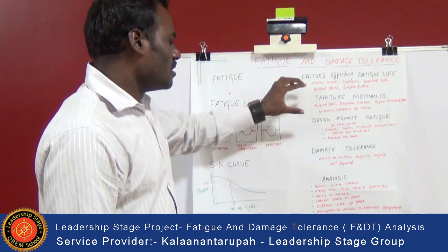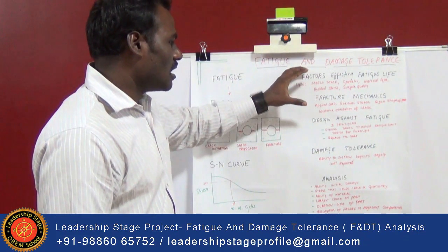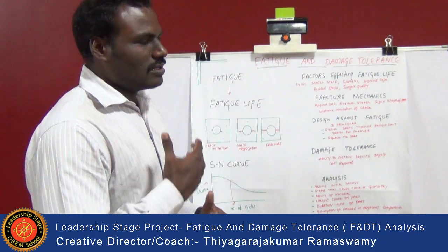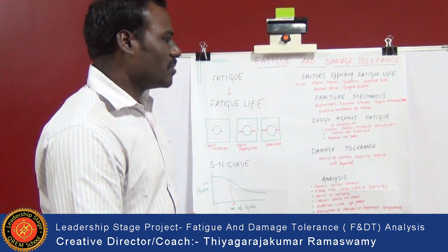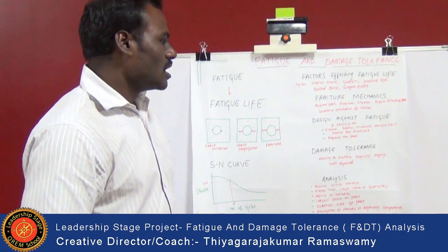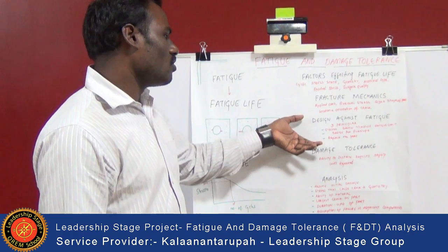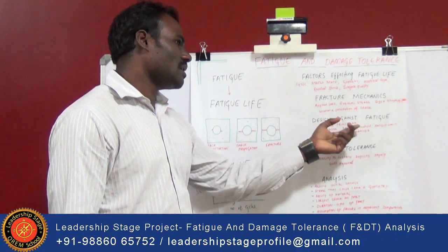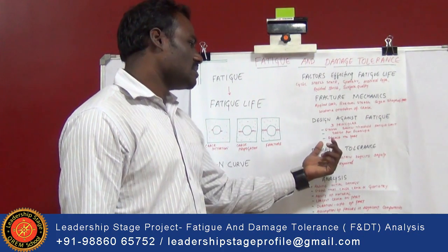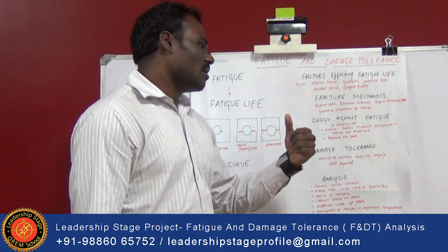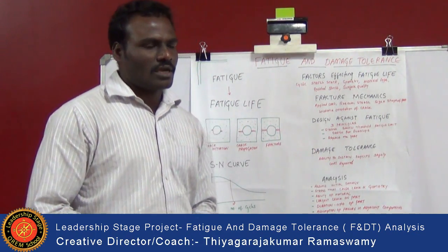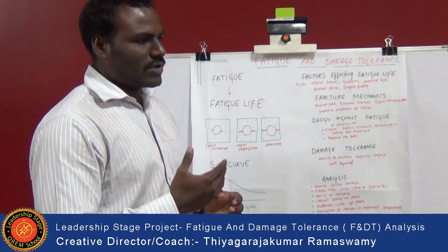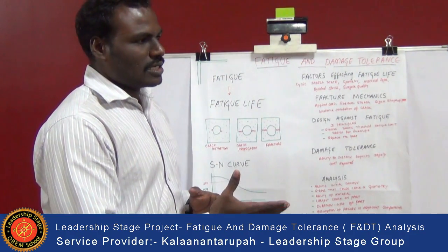Then, after finding out what the activities are which will reduce the fatigue life of the material, in order to improve it, we need to go for a design against the fatigue life. Here, three principles are carried out. First, the stress below the threshold fatigue limit. In the sense, when a load is applied on a material, it